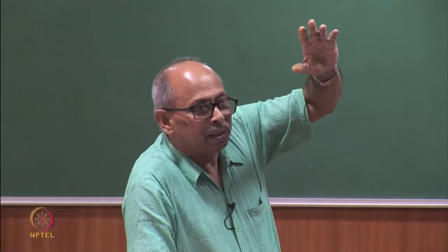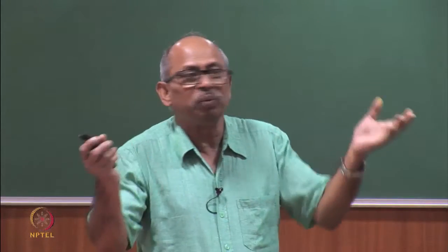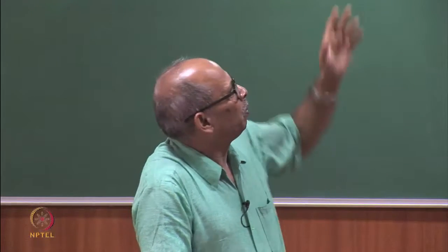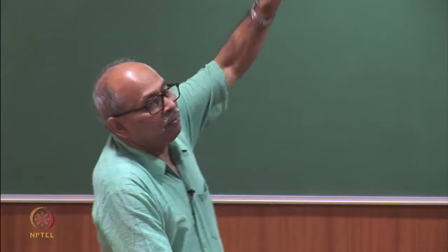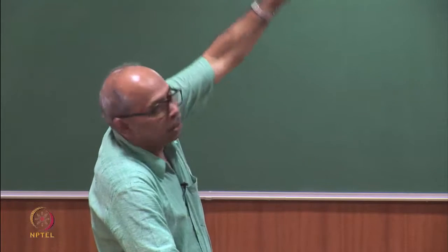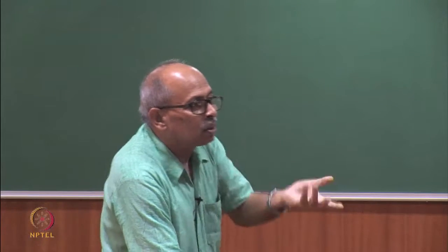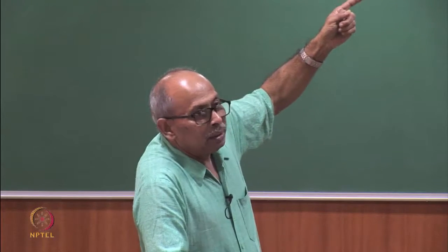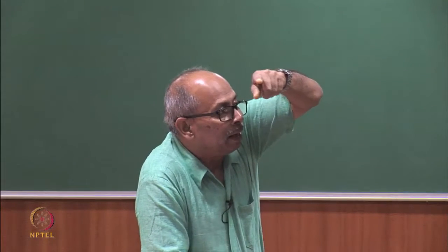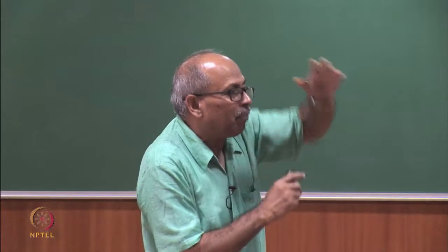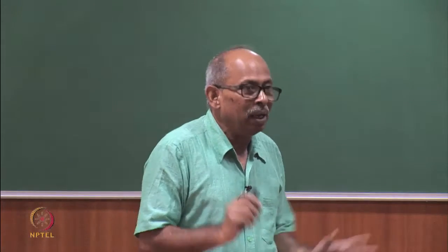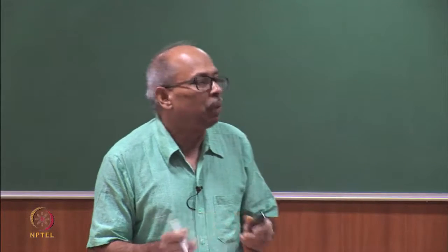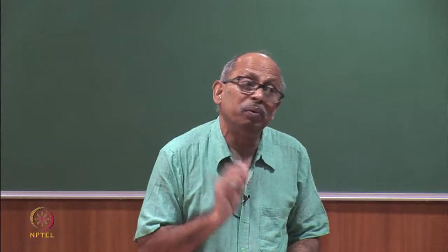A good acoustic design. See, we are using a mic also for such a small room, it is really not necessary if it is done in a proper manner. This should have some amount of reflector on top of this up to a certain point, as we shall see in case of auditorium design, because whatever is spoken here should go back to the end. So, if I put a correctly angled reflector, that will send it to the end. So, acoustic design, if it is done properly, right in the beginning you can put even special absorbers if you know the frequency of the